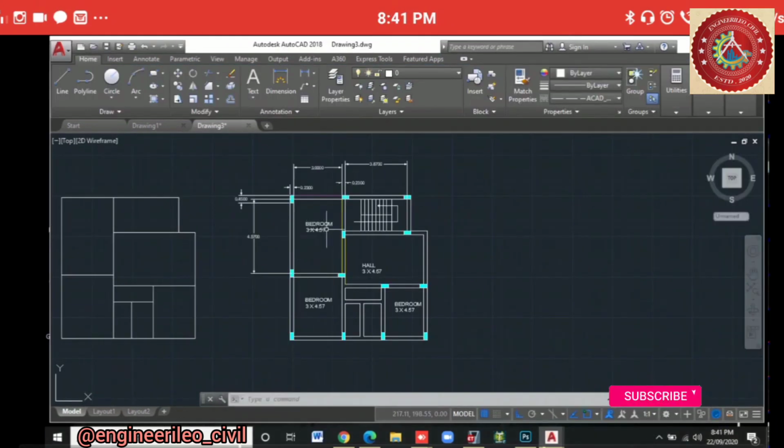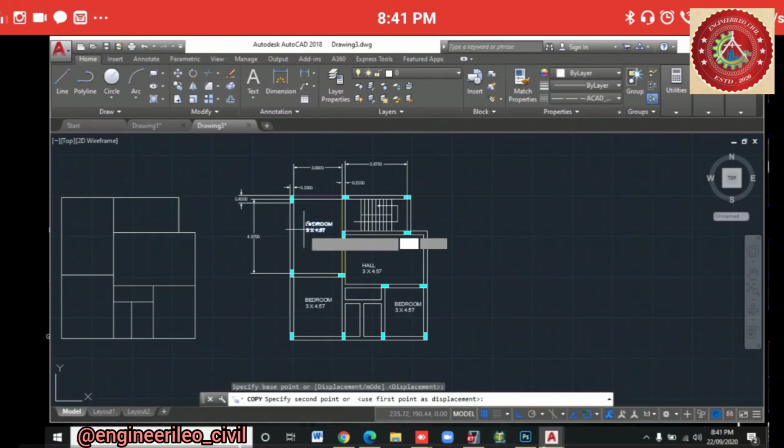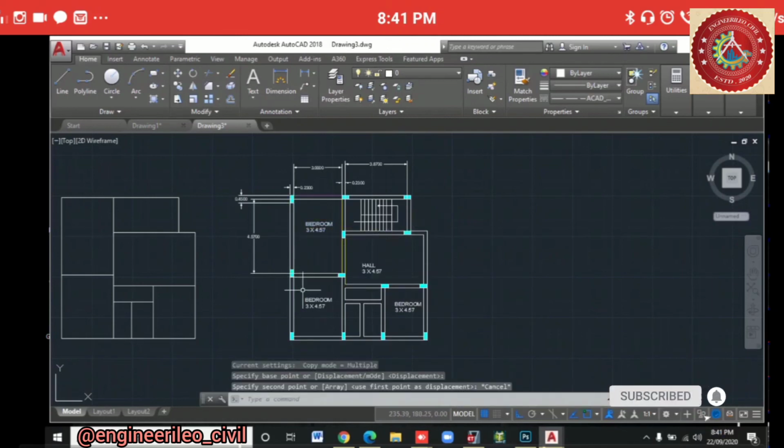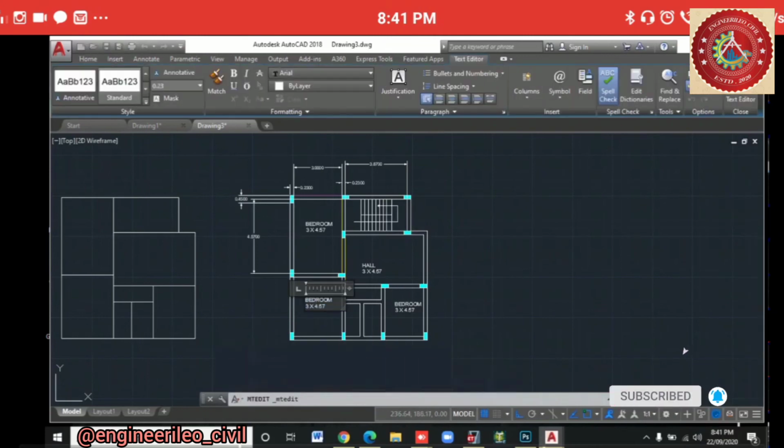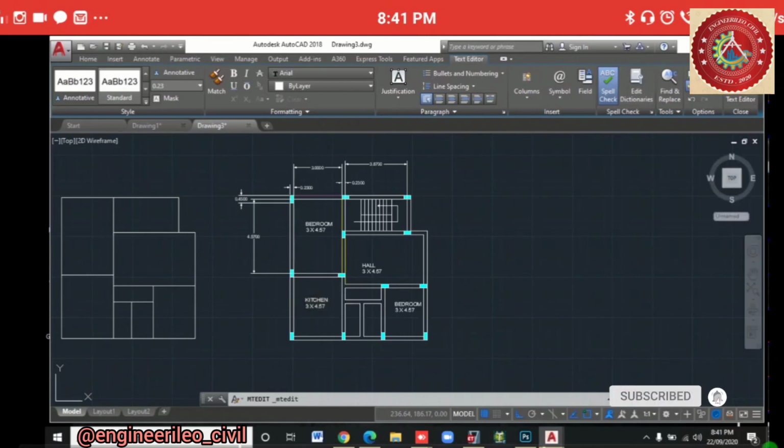Okay, so actually the clip was deleted in between, so I could recap this. We had edited through the text command. We had just given the name with the help of copy. We had selected this command and then gone to copy and just pasted it wherever I want. And after pasting it, I had just gone to the block and double tapped on that and edited that text. Like I want to write kitchen, KITCH, kitchen over here, and then I'll close the command.